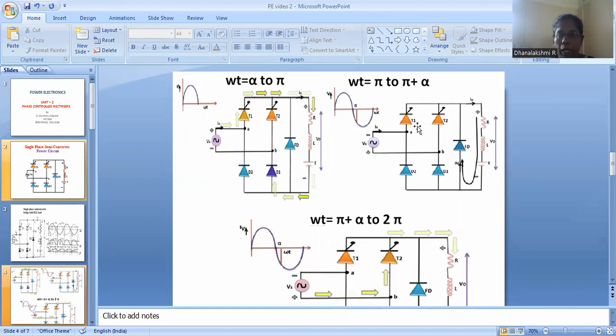Then from pi to pi plus alpha, the energy stored in the inductor has to be released. So a freewheeling path is created here. You can see that the inductor is releasing its energy through this freewheeling diode. It freewheels its energy. So during this period, the output voltage, the load voltage, is zero. Why? Because when the freewheeling diode is conducting, which means that this path is...